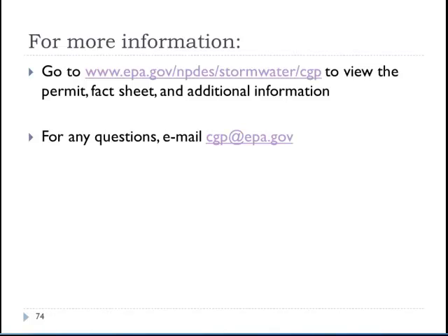There is the option. The frequency of inspection requirements provides you with the option to either conduct one inspection every 7 days or once every 14 days and within 24 hours of a 1/4 inch storm event. So if the concern is that in your area a 1/4 inch storm event will require you to be doing too many inspections, you could choose the other inspection frequency.